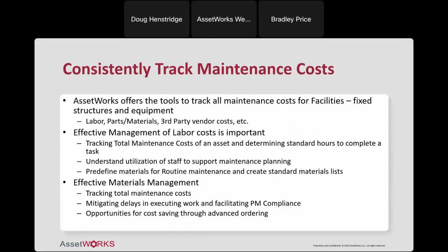The other piece of that is managing materials, right? So if you know the materials you need, the grade and type of lubricant, the size of a filter, the size of a belt, or any other things that would be potentially replaced during preventive maintenance, building or tracking inventory, or identifying a way of managing, having at least the next set on hand, gives you more flexibility in scheduling the work.